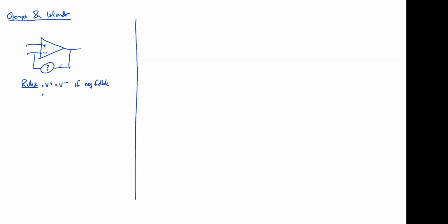One rule is that current going into the output. I'm sorry? Current going into the inputs. Okay, so let's talk about that analysis method. The smart analysis method is to do KCL at the inputs and never KCL at the output. That's because what's not shown in this diagram is that there are power connections here, and those power connections can push current out regardless of the current in, which is the hint for the second rule, which is that the current going in equals the current going out.